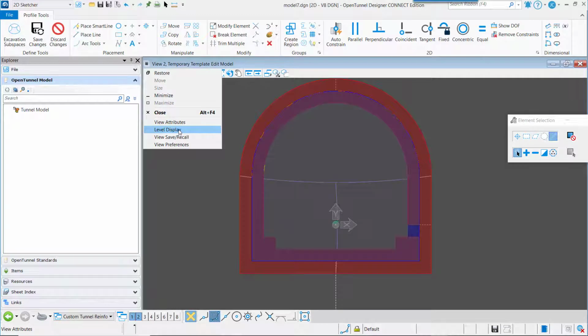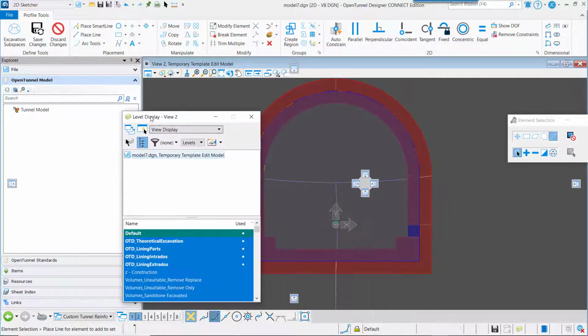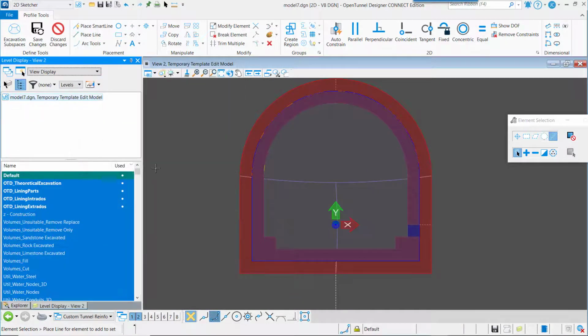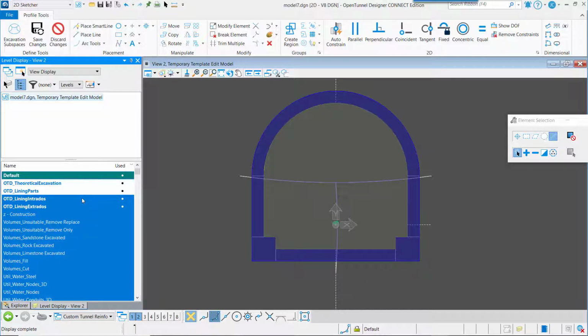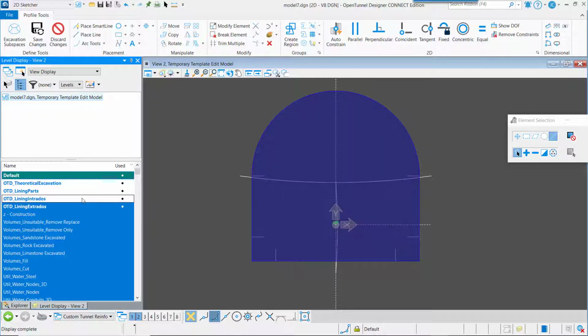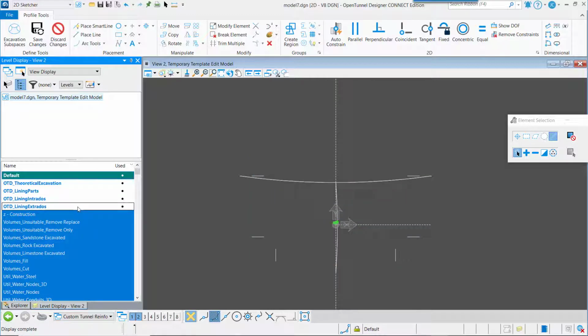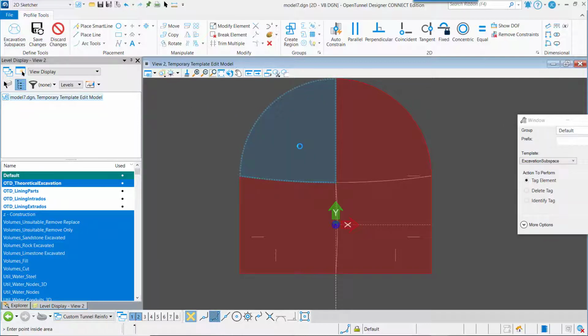And we can remove now different elements by removing in the display list the different levels, so we can define the theoretical excavation inside this cross-section. As I said, the lines defining the excavations are associated, but the regions are not, so that's why they have totally disappeared, because my cross-section didn't find anything.